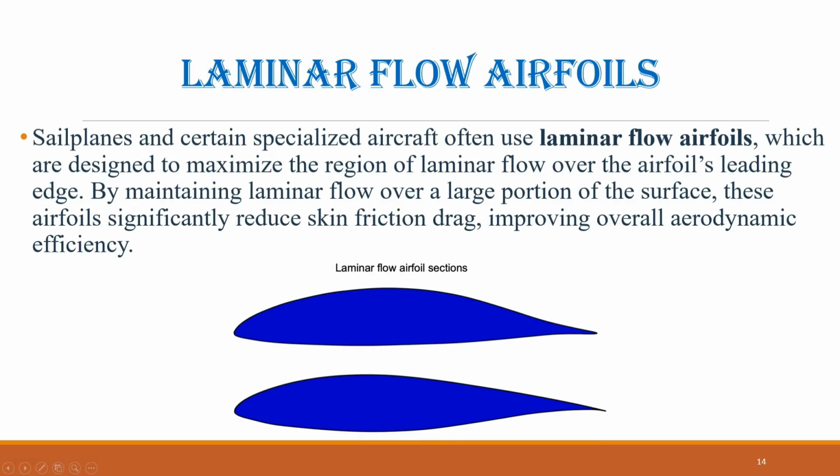Laminar flow airfoils. Sailplanes and certain specialized aircraft often use laminar flow airfoils, which are designed to maximize the region of laminar flow over the airfoil's leading edge. By maintaining laminar flow over a large portion of the surface, these airfoils significantly reduce skin friction drag, improving overall aerodynamic efficiency. A well-known series of these airfoils was developed by Franz Xaver Wortmann specifically for sailplanes, commonly referred to as FX airfoils.